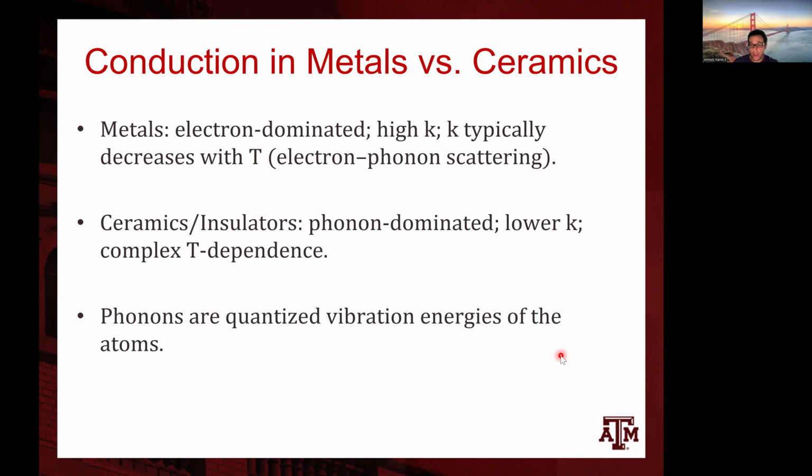Again, depending on the type of solid, whether we are talking about metals or ceramics, the heat carriers would be different. In metals, heat conduction is mainly dominated by electrons, which are the main heat carriers, while in ceramics or insulators, we have those vibrations. Those phonons are basically the quantized energy version of heat.